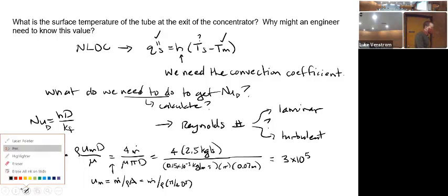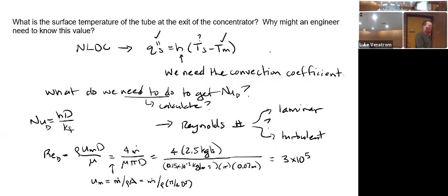You all said turbulent for very good reason. I 100% know why you said turbulent. You were thinking of this thing, Reynolds x sub c is equal to 5 times 10 to the 5. Okay, that's the Reynolds number that we used in external flow to tell us where the boundary layer transitions from laminar to turbulent.